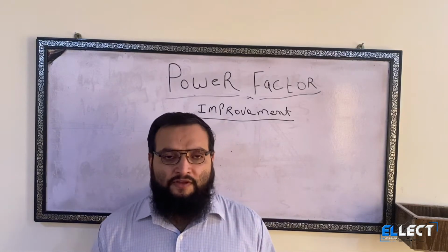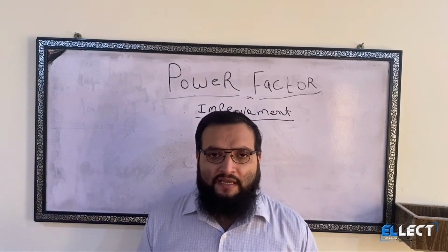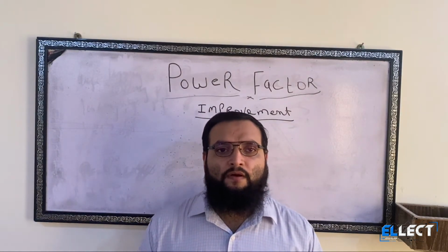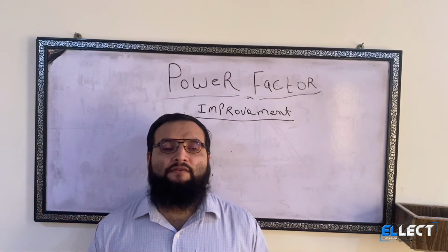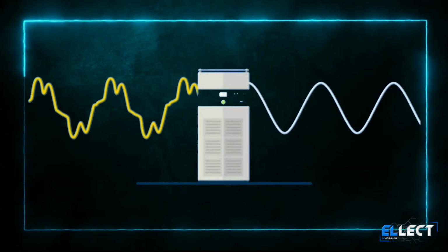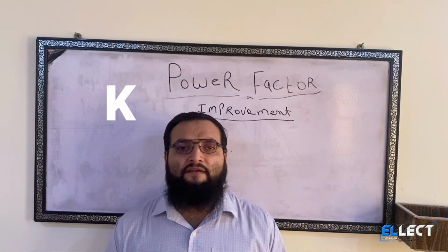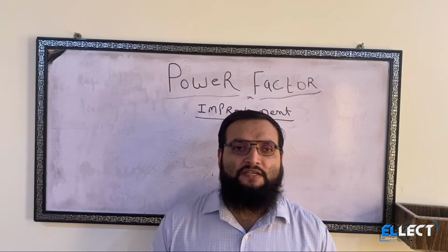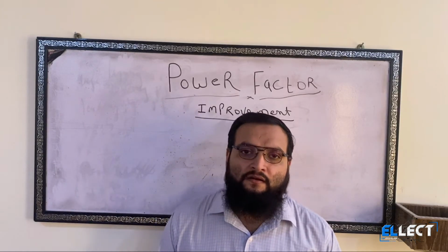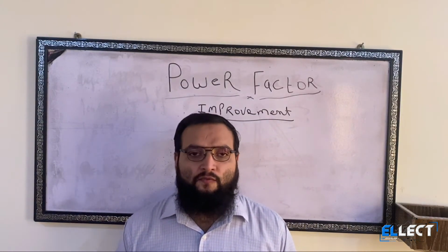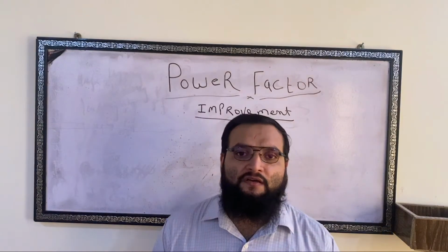We can say that before and after the improvement of the power factor, active power remains the same, but reactive power is eliminated. That is why the unit of the static capacitor is kVAR, because it is also known as the reactive power compensator. So that's why kilovolt ampere reactive is the unit of the static capacitor.